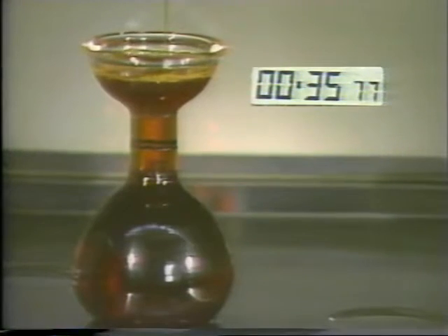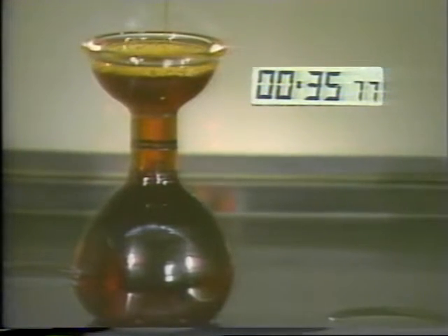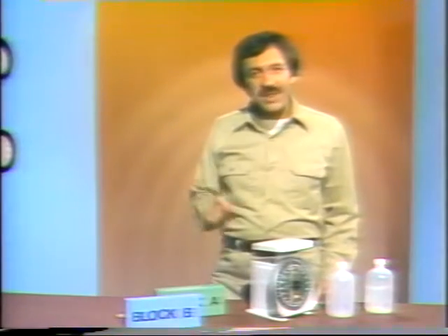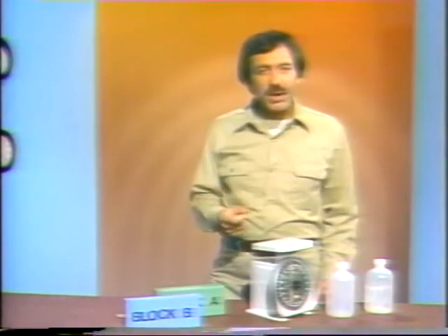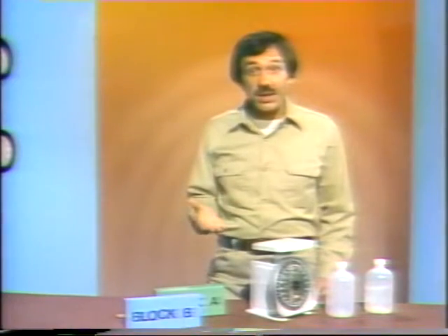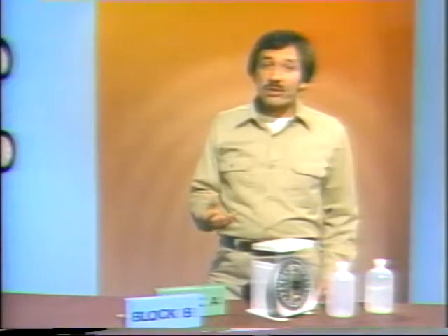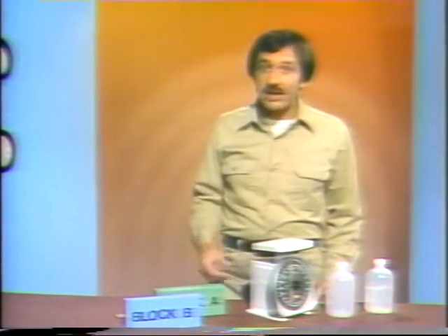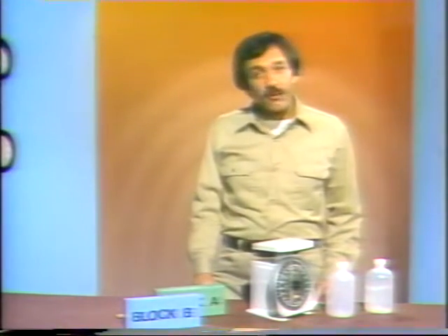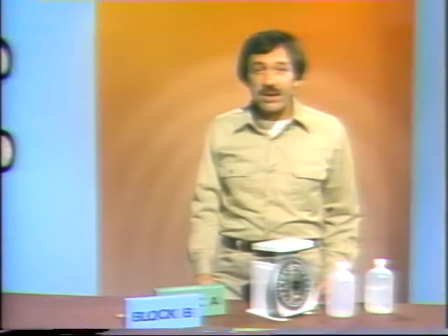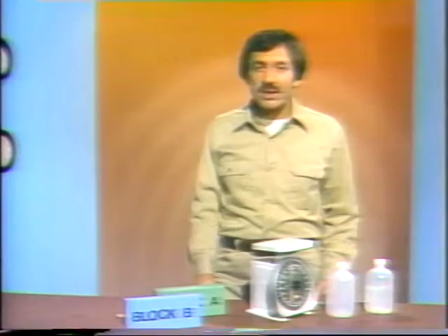Now, viscosity is an extremely important consideration when choosing lubricants. For a lubricant to work, it must be thin enough to flow between moving parts, but not so thin that it will be squeezed out from between them. If a lubricant with too low or too high a viscosity is used, a film of lubricant will not form between the moving parts, and the bearings and lubricated parts of the equipment will be damaged.